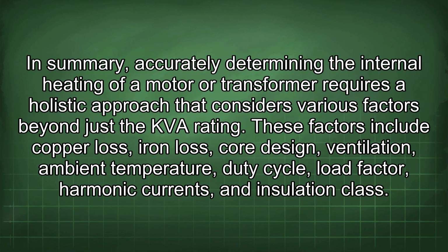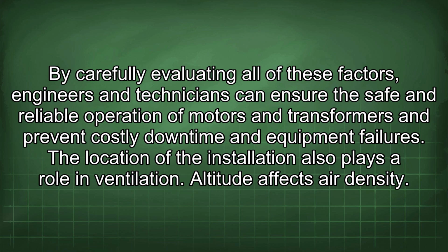In summary, accurately determining the internal heating of a motor or transformer requires a holistic approach that considers various factors beyond just the KVA rating. These factors include copper loss, iron loss, core design, ventilation, ambient temperature, duty cycle, load factor, harmonic currents, and insulation class. By carefully evaluating all of these factors, engineers and technicians can ensure the safe and reliable operation of motors and transformers and prevent costly downtime and equipment failures.